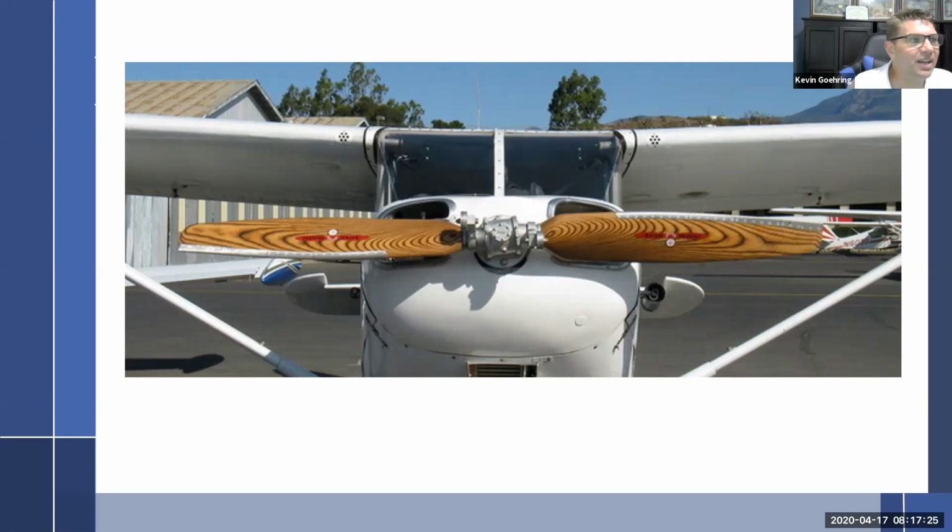But this was an automatic propeller, 100% not pilot controlled, and it sensed air loads. So it used centrifugal twisting moment and aerodynamic loads and RPM to find the right pitch for what you wanted to do. And to try and explain this, it hurts, just to understand what it was doing and how it works. But I'll kind of show you something a little bit without making you have to memorize it. I'll say, well, this kind of works like this.